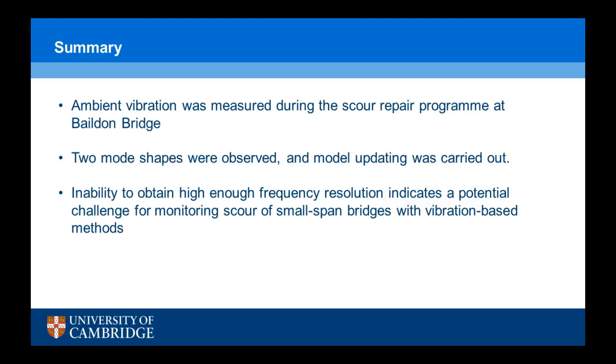So in summary, ambient vibration was measured during the scour repair program at Baildon Bridge. We detected 2 mode shapes, and according to them, we were able to successfully update the model. The inability to obtain high enough frequency resolution indicates a potential challenge for monitoring scour of small span bridges with vibration-based methods.